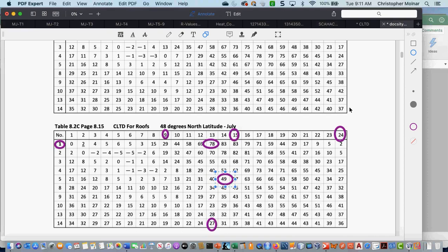Well, this is all relating to a roof with an attic below it? Yeah, but there's other tables for roofs with no attics. What if you had a situation where you have a flat roof with no attic below it? Believe it or not, you use it more as a wall, because it's flat. There's no space inside of that. So your CLTD is basically zero. But I know the flat roof being a dark roof and being right in the living area, it is like the craziest amount of heat gain through it you could imagine. Yeah, that's where you look at that.